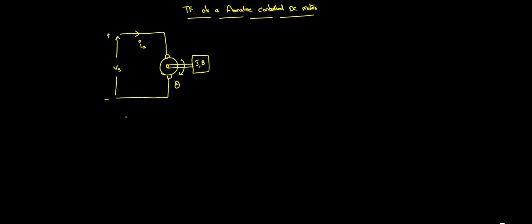Whenever you give supply to the electrical motor, the winding is made up of resistance. When the current flows through it, it creates a magnetic field, which is due to the inductance, and it opposes the main field. That is what is called the back EMF. These are the main electrical equivalent circuit elements of this particular system.